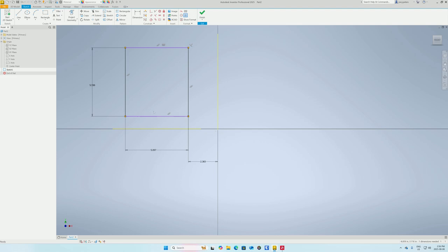So when you're getting near the end or when you have a problem, it's good to look at this corner to see how many degrees of freedom are left. A lot of the errors are that you're over constraining something.